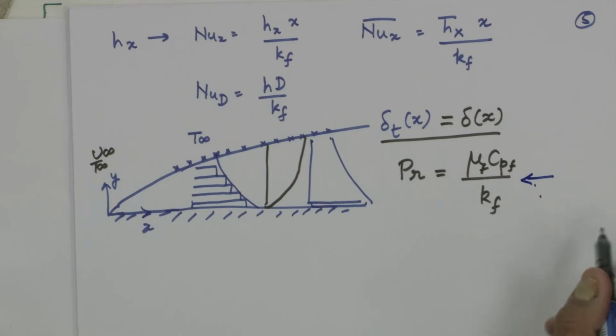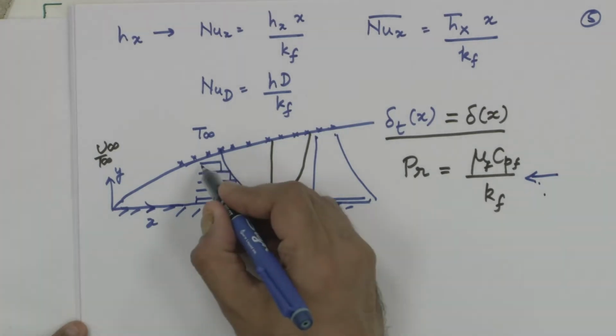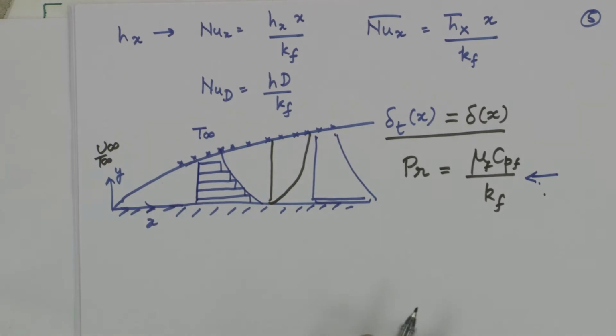In the last module, we ended with the idea of Prandtl number, which is a very important non-dimensional quantity with respect to heat transfer. Prandtl number, we said, is given by the formula mu Cp by K, and it decides how effective momentum transport is vis-a-vis heat transport. Both transport of momentum and transport of heat happen because of certain physical properties of the fluid.